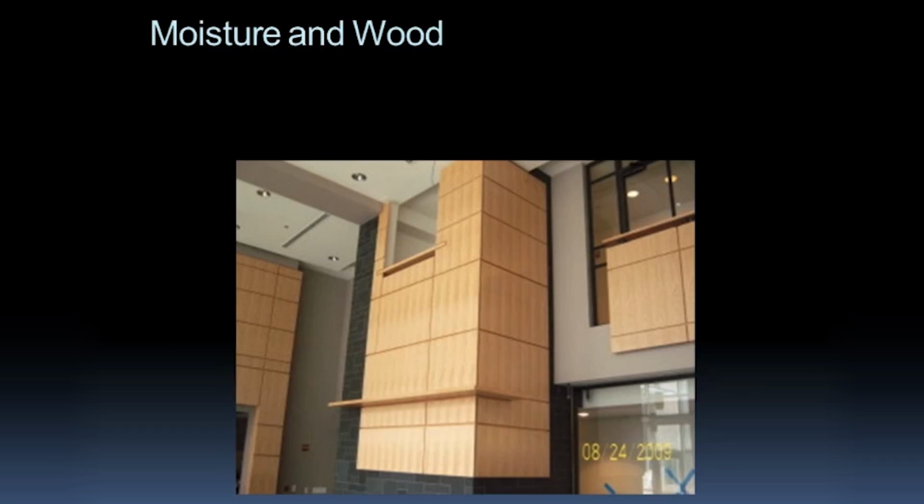And the contractor, of course, said, well, what's wrong with your panel? I mean, it was wider than that the other day, and now it's smaller than that. So what's causing this? And I think my response was, well, I think your building is causing that. And sure enough, it was, in fact, the building. The relative humidity, I think, was in single digits or certainly in the low teens, which is what was causing the shrinking of those panels.